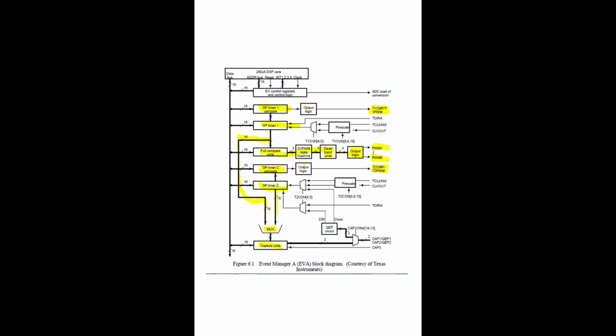That mux operation you already know. So any one of the timer 1 and timer 2 values will come out here. Let us take the timer counting from 30 to 0, decrement counting: 29, 28, like that it will count. At one point of time you want to know the present value of the timer. That value will be captured with the capture unit, and it can be displayed on the display for the user.